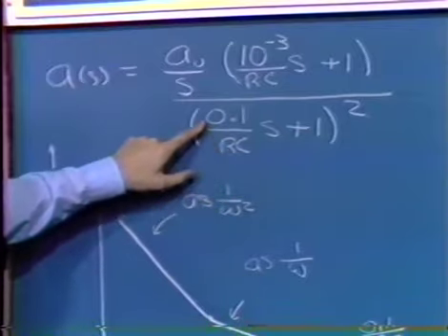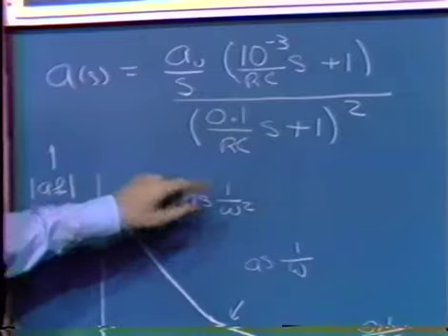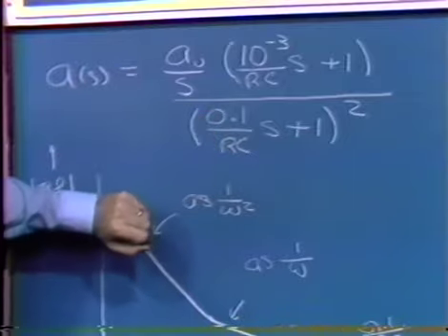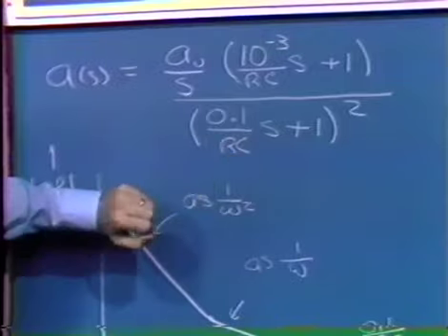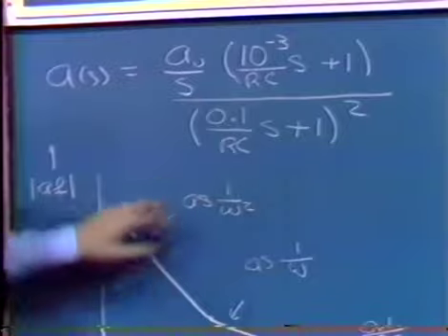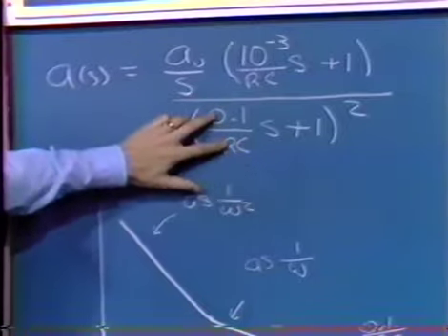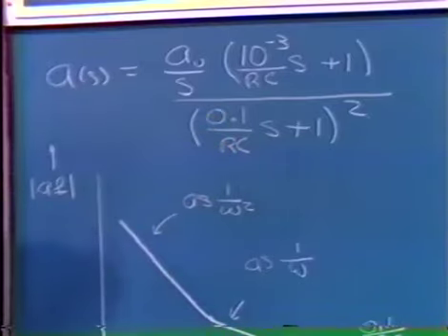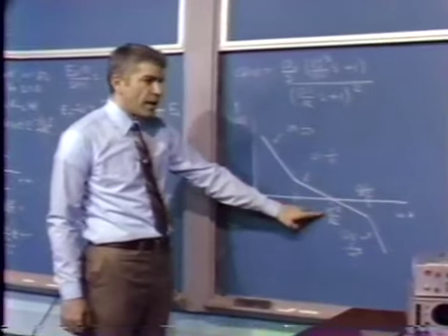Again, recognizing that we're going to shoot for a crossover in the amplitude control loop that's 1/100th of 1 over RC, let me put 2 poles that will provide additional filtering to signals at and above 1 over RC, the sort of hash on our envelope detector. Let's put a couple of filters that occur a decade below that and in fact are located 1 decade above our nominal crossover frequency.